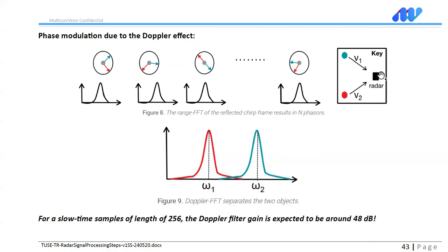And this roll is a function of Doppler processing. Doppler, the velocity of the target. So if you have two targets hidden in the same range bin, when you take the FFT, you can separate them. Two targets will be separated. And now you have two targets. You say targets become resolvable.